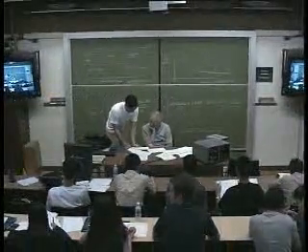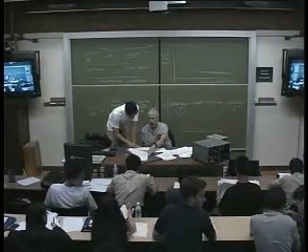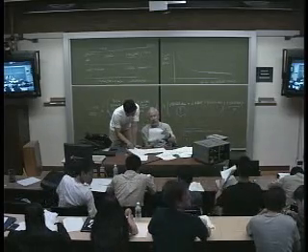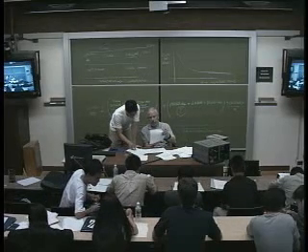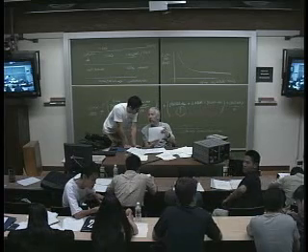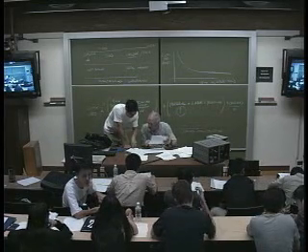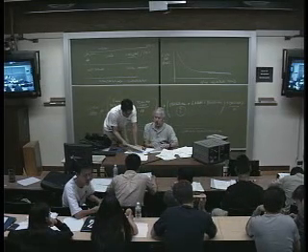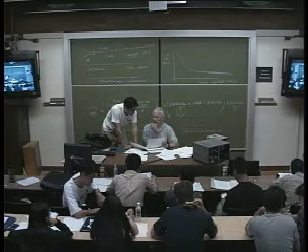Two questions. One was, why do you need this up here? That's the tail current source, right? But I thought you have a current source down here. Tail current source, right? It's this guy. Why would you need two current sources? For the common mode range, common mode swing, right? This is just that current source. So why do you need this current source? Just for the folding. It provides current for this stuff, right?